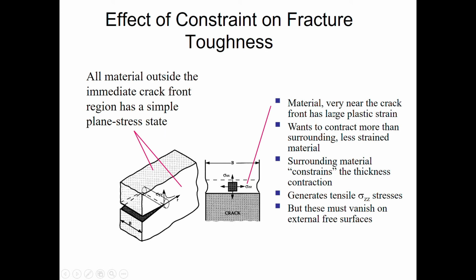Material very near to the crack front, for example if I take this point, has large plastic strain, and it wants to contract more than the surrounding less strained material.